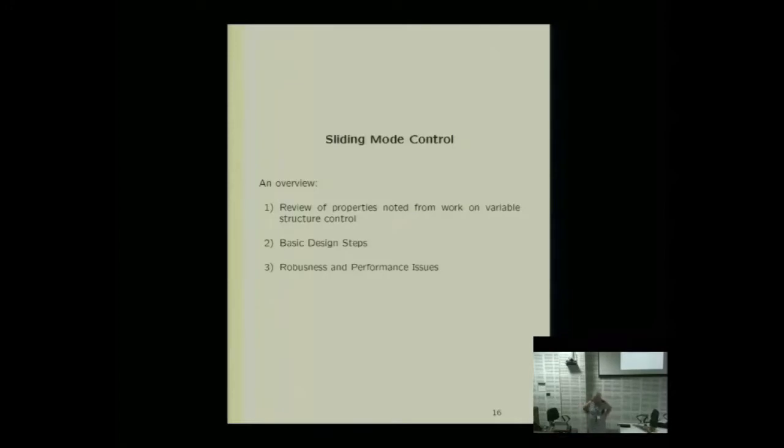I mean, my colleagues from the H-infinity control community were not wrong in that they said to cancel the signal exactly, you need to know what it is. That's clearly the case. Where they were wrong was that they thought I was using that information directly to cancel the signal. What in fact was happening was by the properties of the discontinuous control signal, on average, what that was doing is reconstructing the sinusoid. Okay, so on average, it is giving you the measure of the uncertainty exactly.